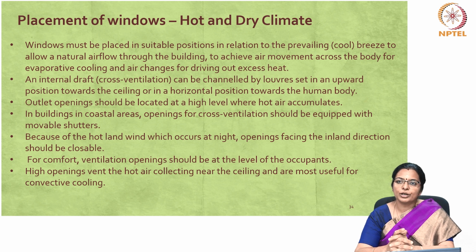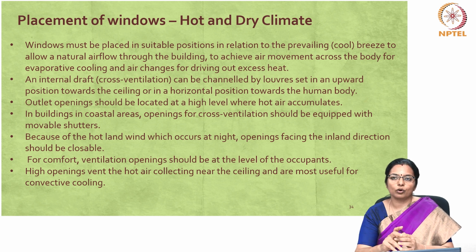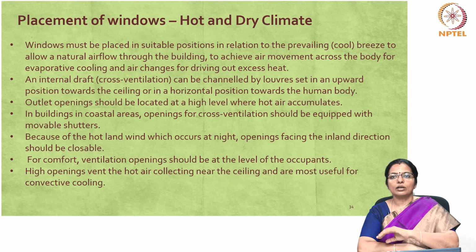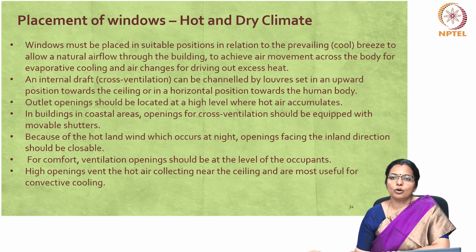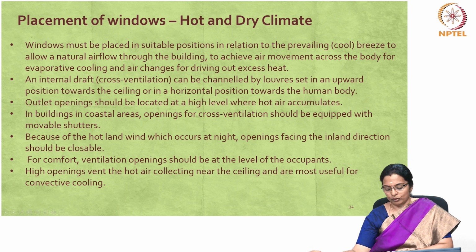Outlet openings should be located at a high level where hot air accumulates. In buildings in coastal areas, openings for cross ventilation should be equipped with movable shutters. Because of the hot land wind which occurs at night, openings facing the inland direction should be closable. For comfort, ventilation openings should be at the level of the occupants. High openings vent the hot air collecting near the ceiling and are most useful for convective cooling.